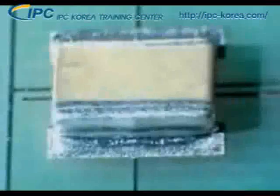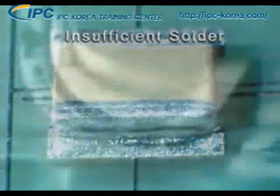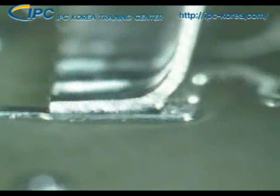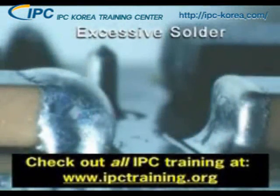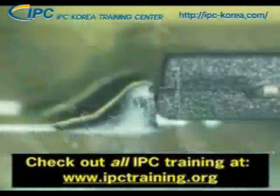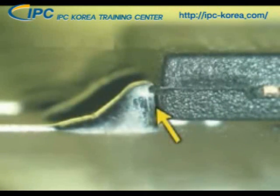This is what insufficient solder looks like for our 3 components. You can see that the solder fails to meet minimum fillet heights from our dimensional criteria, and there is no evidence of a properly wetted fillet. When the solder extends onto the body of a surface mount component, this is considered excessive solder. Excessive solder is a defect for either class of component. As an exception to this rule, solder may touch the body of plastic SOIC or SOT components.